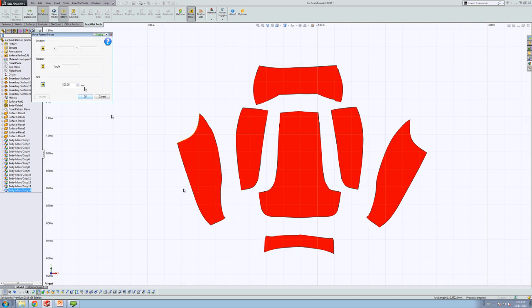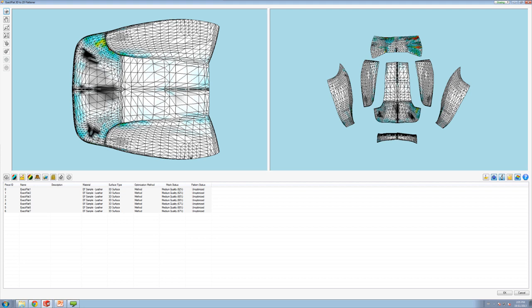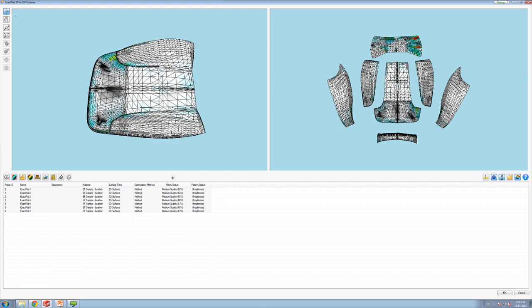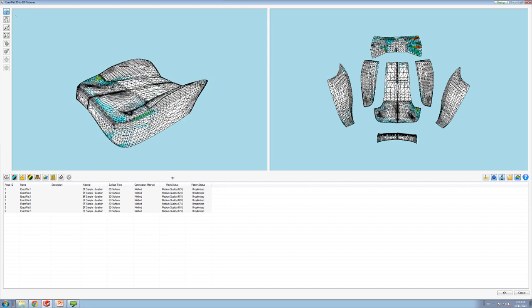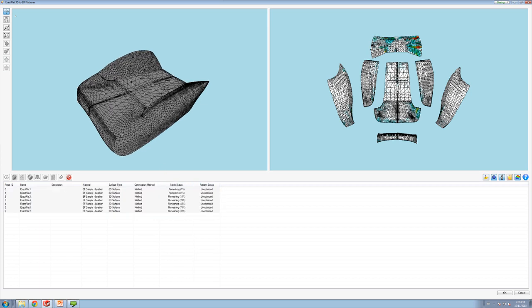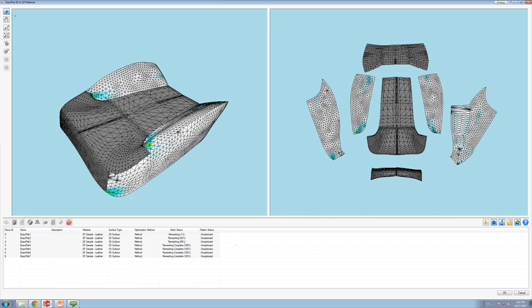We're going to now move into our flat pattern environment. What this environment does is optimize the fit of a flat pattern. It is designed to flatten complex surfaces. The first part of the process is we're going to create a mesh which is optimized for analysis. The mesh elements are going to be redrawn, and they'll be optimized in such a way that when our flattening algorithms run, we will decrease the solve time and increase pattern accuracy.